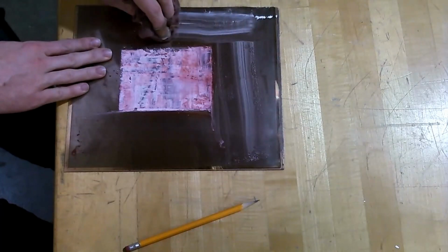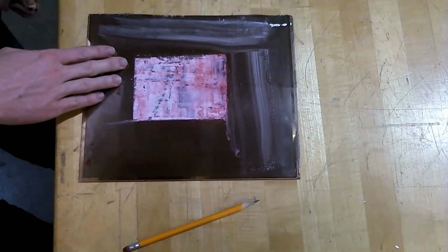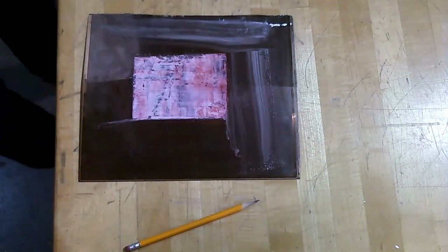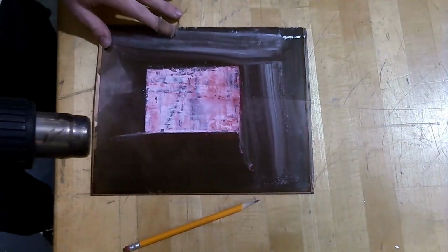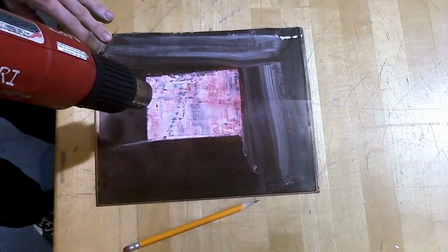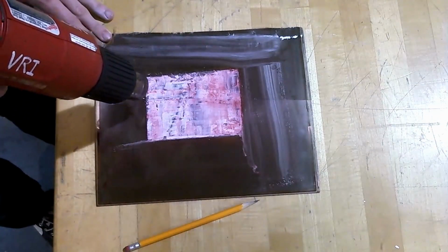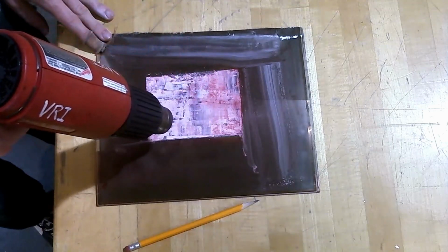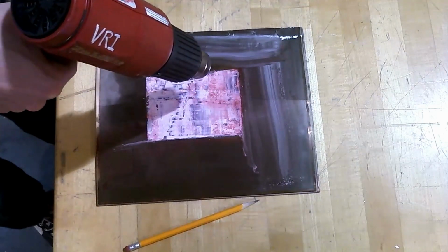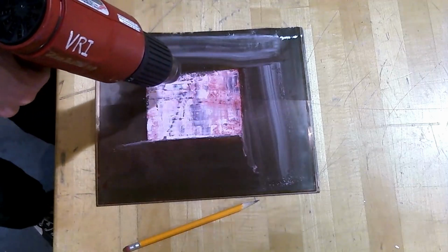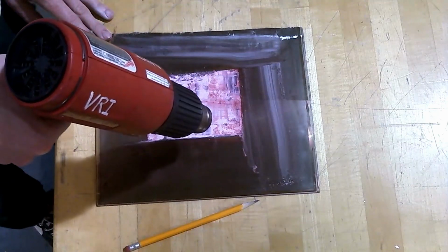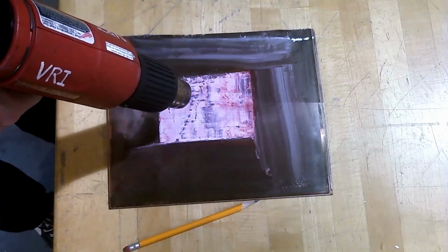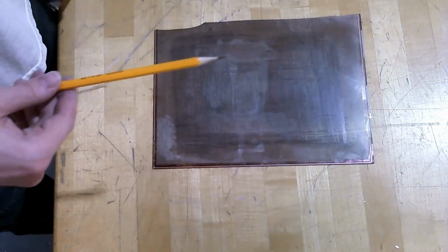In the next step, we are going to deposit the carbon onto the opposing side of the panel. For this process, I just used a pencil and literally just drew on that other piece of conductive glass I have, once again, on the conductive side. You want to create just a really thin layer of pencil lead, which is going to act as our catalyst and speed up the whole process and make sure that we create that circuit.